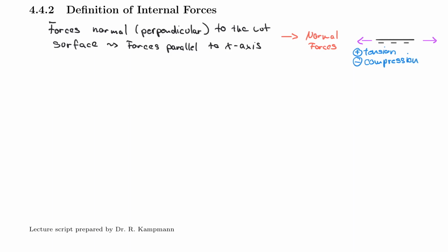And that is very important to understand, because sometimes engineers blindly communicate if a system is in tension or in compression. So if you see a normal force that is negative, that would mean that this arrow here would be flipped around and would actually push on the system on both sides, and therefore the system would be in compression, whereas if you pull on it, it's in tension.